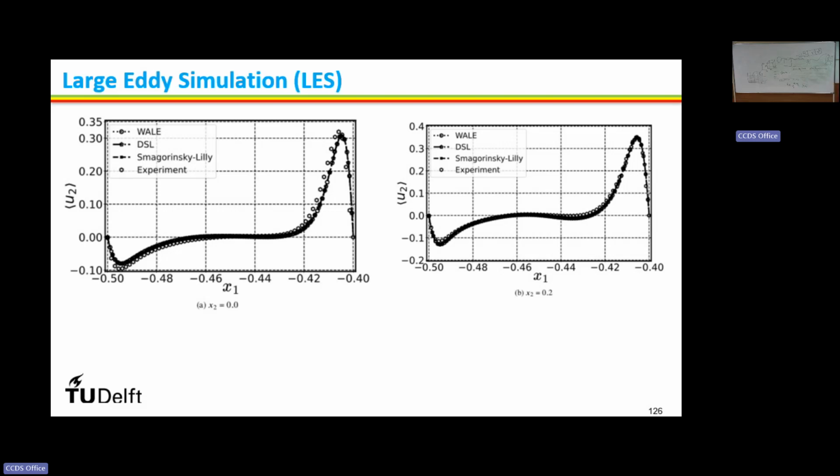the accurate one, the central difference scheme, is that the central difference scheme is the most accurate, but it is susceptible to numerical instability. The result is less stable. Once you do central differencing instead of upwinding, the result will not be numerically stable, right? Because you don't respect the direction of the flow.